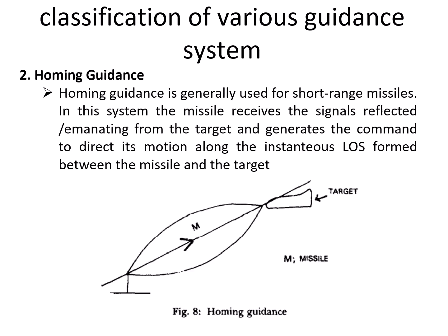Another is the homing guidance systems, where your transmitter and receiver are both fitted in the missile as well. So homing guidance is generally used for the short range missiles. This system will receive the signal reflected or emitted from the target, like heat seeking missiles, where the missile will be seeking the reflected electromagnetic wave, so which will be the seeker kind of missiles will be using, where these receivers are fitted in the missiles.